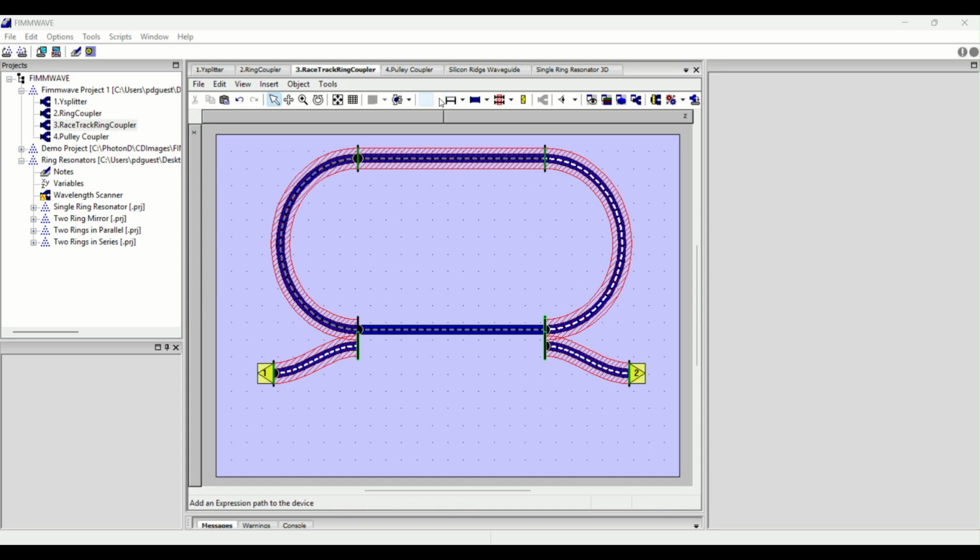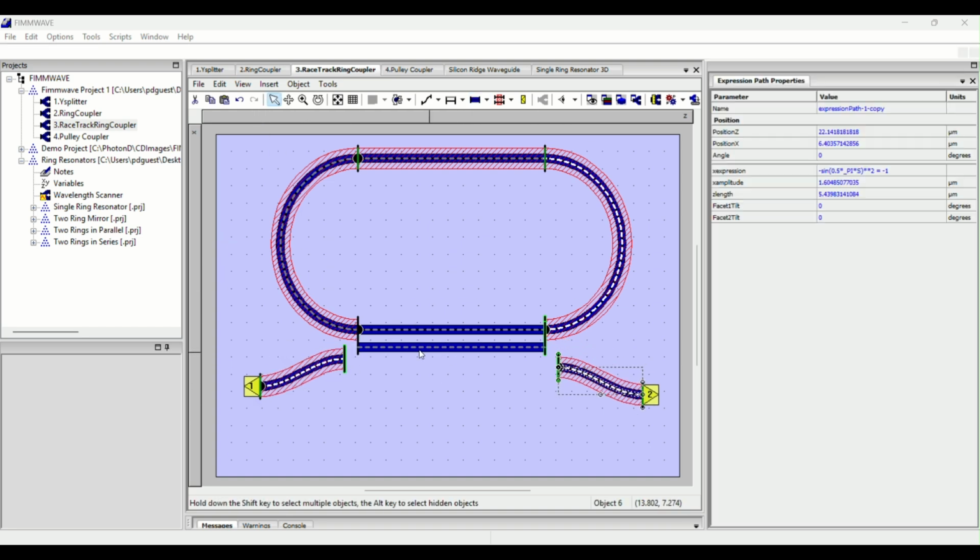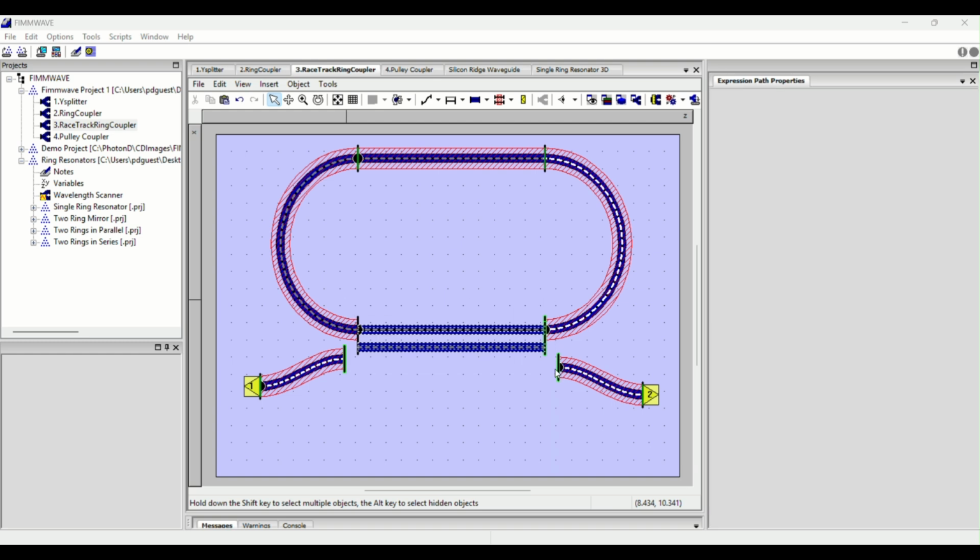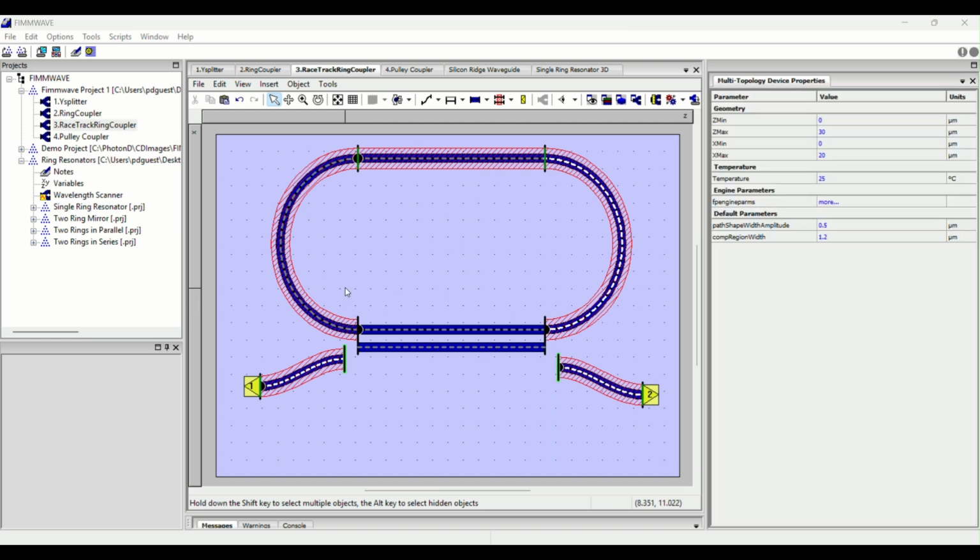What we'll do is we'll use a subpath. So this is my subpath button here, and I can drag on a subpath from here and add my waveguide back on. Now, when we use a subpath, this entire block is just considered as one path, rather than as two separate paths which need to have a span region. So we can actually simulate the coupling between these two paths just using a path computational region.